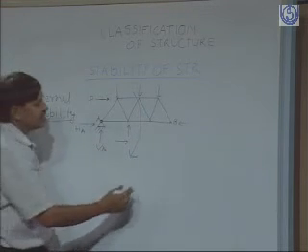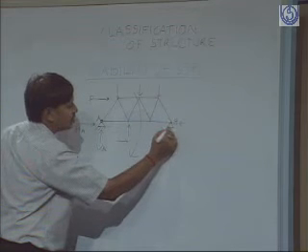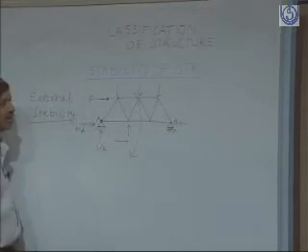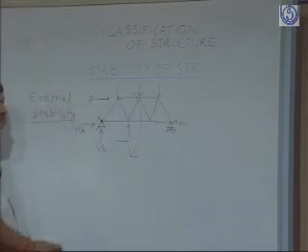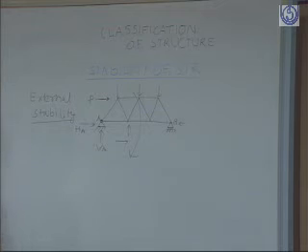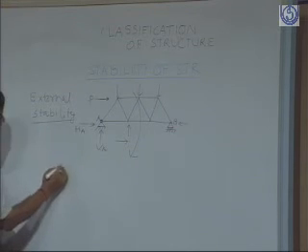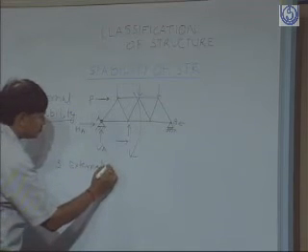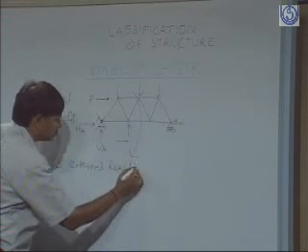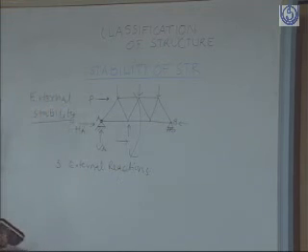So it has to be restrained here also, maybe in a single direction, either vertical or horizontal, so that it can restrain it from rotation. So at least three external reactions are necessary for a plane pin jointed structure.